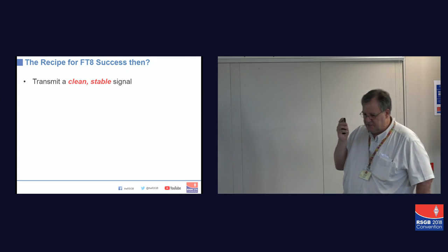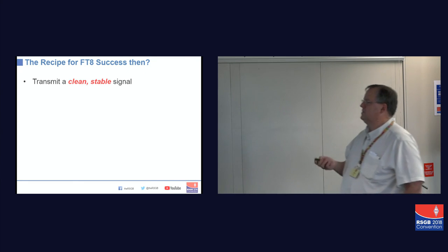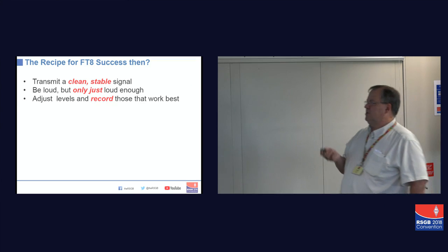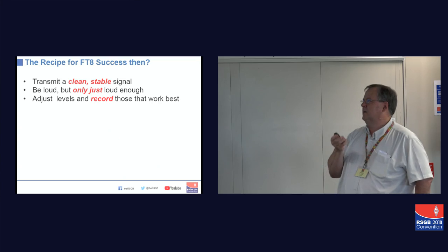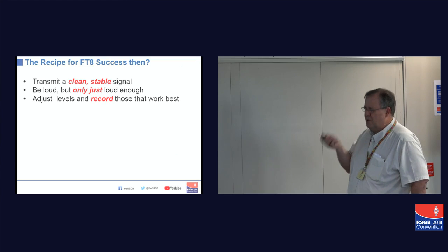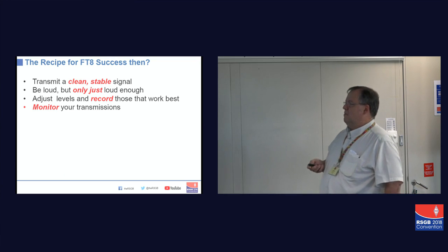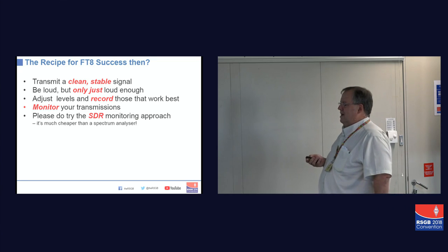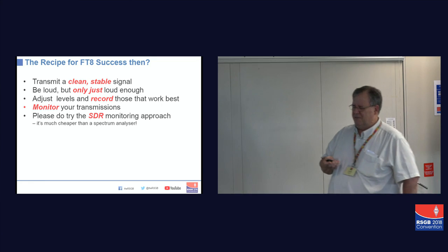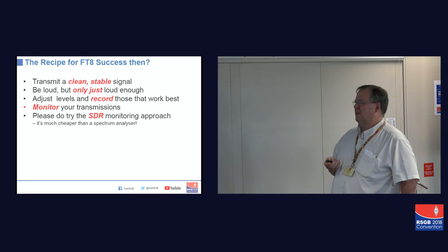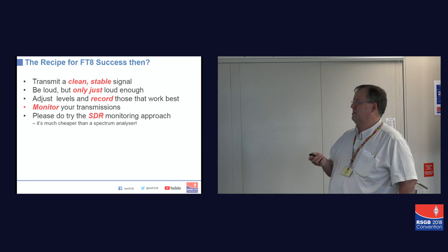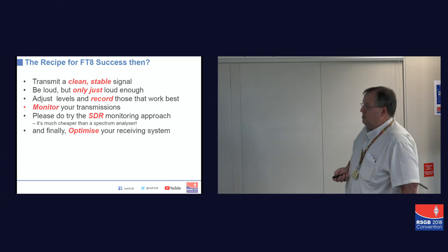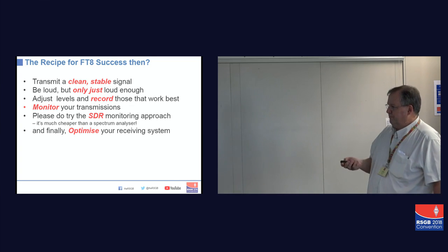So, recipe for success. Transmit a clean, stable signal. Be loud, but only just loud enough. Adjust your levels, understand your levels, and record them so that you know how to set them again. Monitor your transmissions, unlike the bad guys. And if you haven't ever played with these SDR thingies, have a go, because it was a doddle, and it's so much cheaper than a spectrum analyzer, and also you can put it in your pocket. And optimize the hell out of your receiving system.